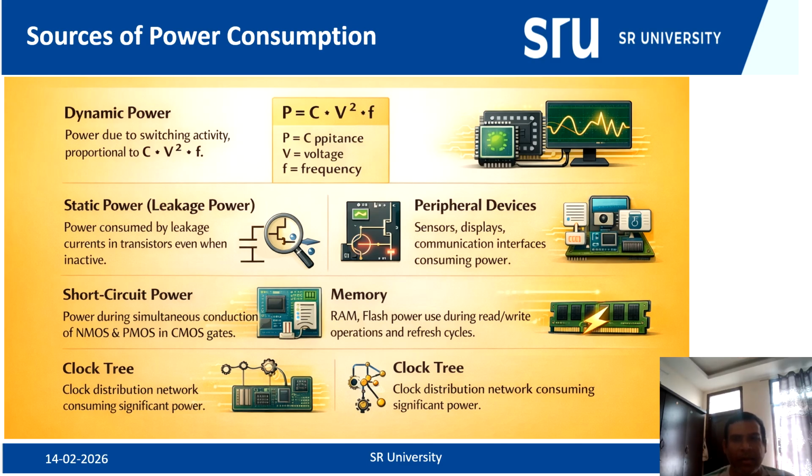It means the circuit is in an idle state whenever we are not using it, like a CMOS inverter where we are not applying any voltage at the input terminal. At that time also there will be leakage power consumption due to the flow of leakage current. So it mainly arises due to the leakage current in the transistor.